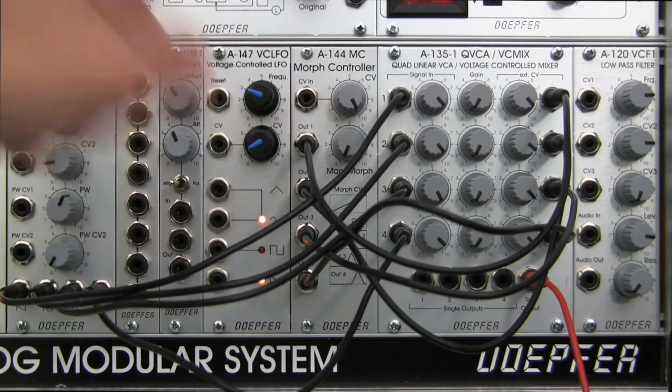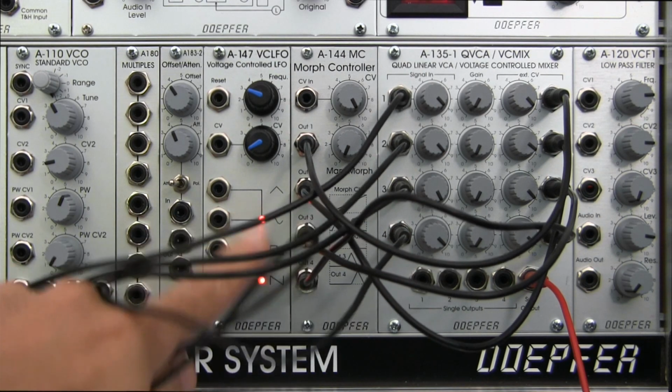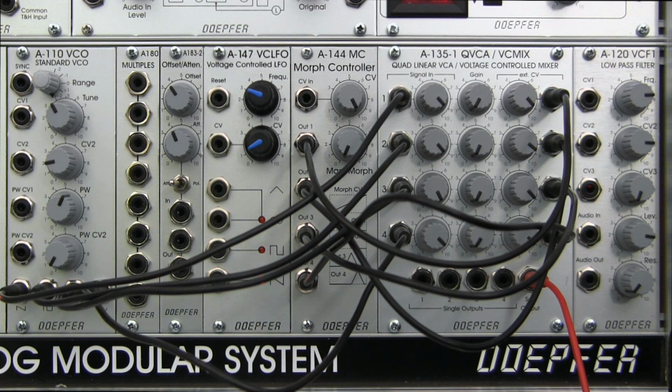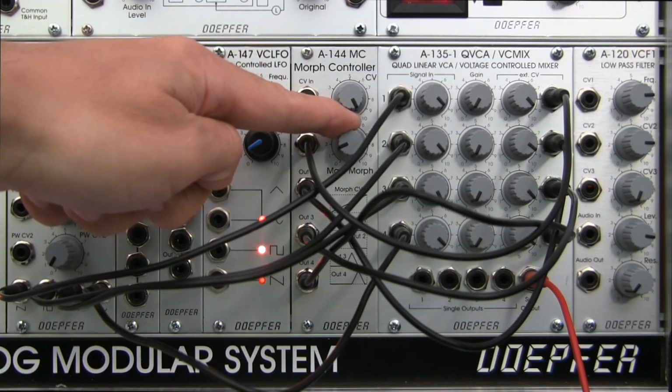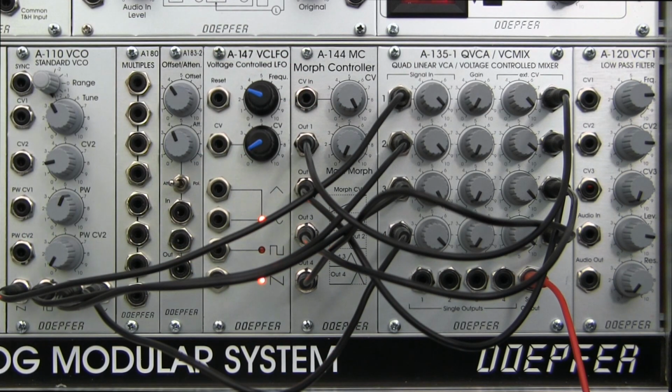So that's manual morphing. And then there's also the so-called automatic morphing that most of us know as modulation when we're dealing with the modular. And usually that's going to involve taking a CV signal from an external module, like a A147. This could be an LFO signal, or it could be something like an envelope generator. Basically anything that produces a low-frequency signal that can sort of create this manual movement that we're doing with our hand via a CV. Now there is one kind of fine print to that.